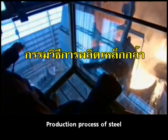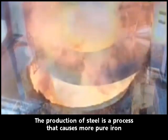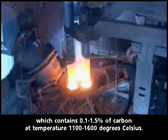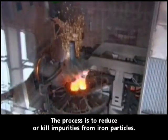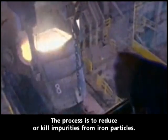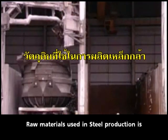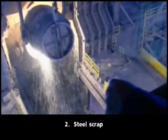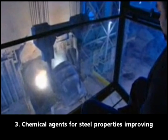Production process of steel. The production of steel is a process that makes purer iron, which contains 0.1 to 1.5% of carbon, at a temperature of 1100 to 1600 degrees Celsius. The process is to reduce or remove impurities from the iron. Raw materials used in steel production are: 1. Pig iron. 2. Steel scrap. 3. Chemical agents for improving steel properties.